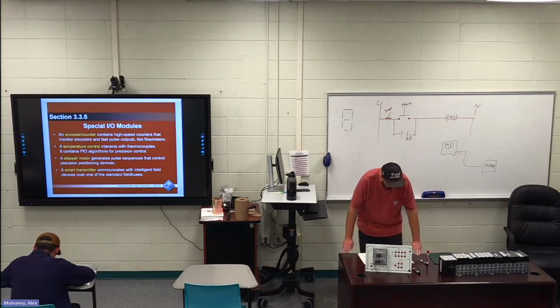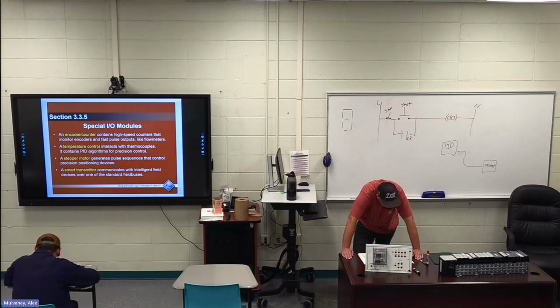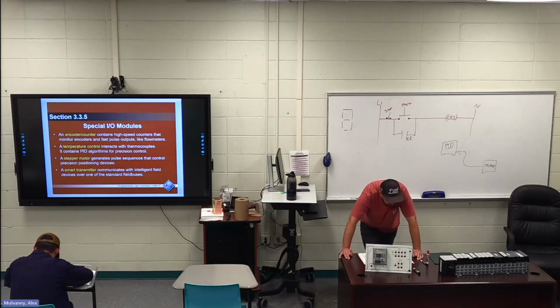Instruction list 415. First few sentences are highlighted. Like structured text, instruction list programming is text-based and done with a text editor. Unlike structured text, instruction list is essentially only readable to experienced programmers. Each program line is a short, abbreviated instruction called a mnemonic. Most are just a few letters long and look like LD, ST, and JMP.